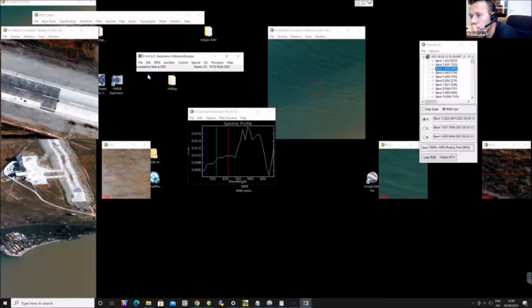The reason we fly 4 flight lines is to check for consistency, that you have the correct offset. We always recommend to process all 4 combinations, like 1 and 3, 2 and 4, 4 and 1, and 3 and 2. Because then you will get 4 different combinations of flight direction in the cross, and those should match the offsets. If they don't match, then you have a problem with one of your inputs, right?